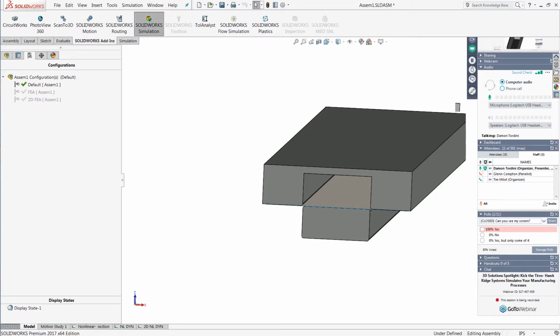But as you probably imagine, this is a very complex type of analysis, which could take a long time to run and would require some pretty particular inputs, things like the right material model. And as far as SOLIDWORKS simulation goes, the nonlinear version of the Cosmos solver can do a lot for what it is, but it does have some limitations. One of the issues with the Cosmos solver is that sometimes if there is buckling, especially in a contact problem like this, it can be difficult for the solver to get over. And the solve times can be challenging if it's a much more detailed mesh.